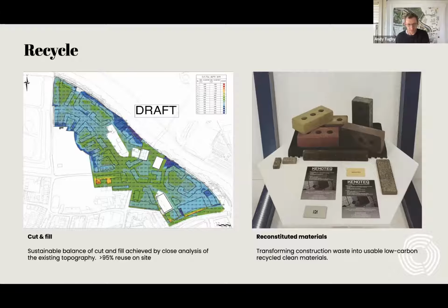Other recycled materials: any sheet piling or rebar that we use, we'll hope will be recycled. So we're looking at a sheet piling product called Eco Sheet Pile Plus, which is a very green steel sheet piling product, as well as green rebar. And we're looking at chem-free concrete solutions, as well as the potential for possibly using fly ash from an energy from waste plant within the concrete. But these are things that are under examination at the moment.